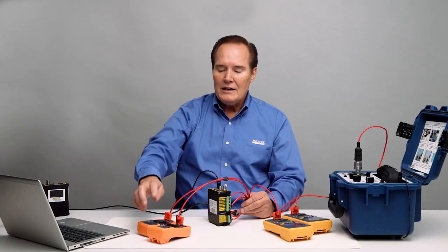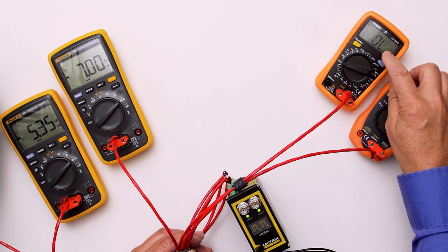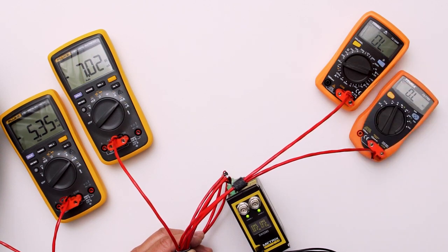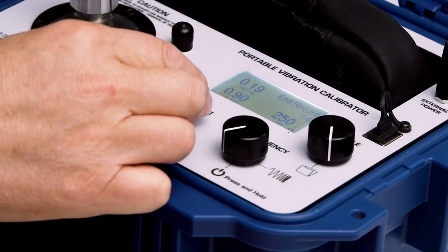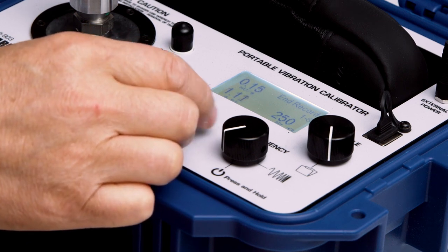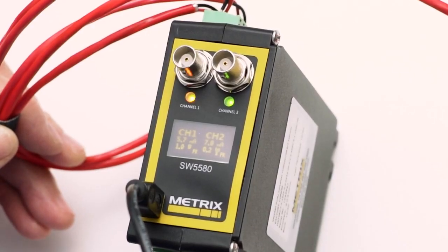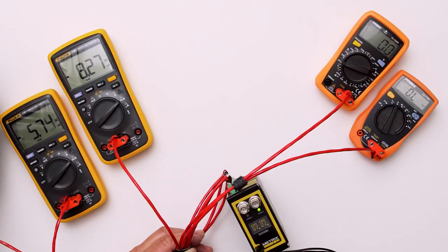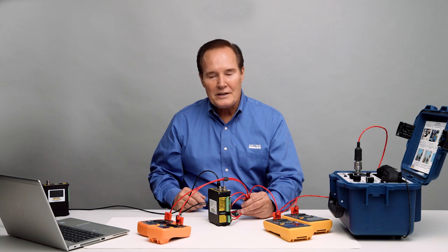And when you see that, you'll see that the alert, which is here, you'll see the resistance change when that relay changes state. Now this is a mechanical relay, I expect the short. So let's see if that really happens. Let's go to 1.1, about 3 seconds. Relay changes state, see the flashing yellow, we're in alert. And you can say, okay, we have a short, we don't have any ohms, and that's because it's a mechanical relay and not a solid state relay. So it's a short, and that makes sense.